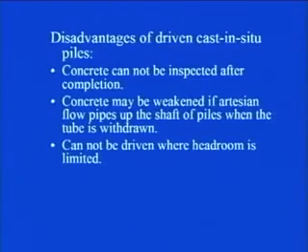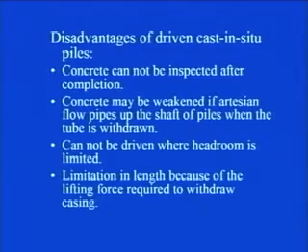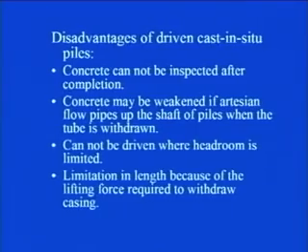It cannot be driven where headroom is limited. Then there is limitation in length because of the lifting force required to withdraw the casing. Let us say in the case of an uncased pile you have to take out the casing. So, in the case of higher pile length, the lifting up of the casing becomes more and more difficult in case of driven cast in situ pile.